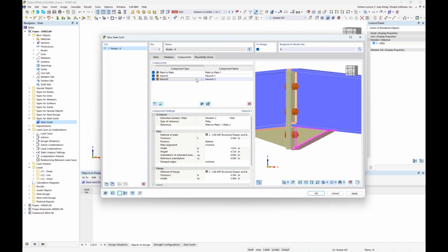We move over here on the right-hand side, and we want to make those exact same changes that we just did to the left-hand side. So we'll modify here the thickness to 0.5 inches. We want to modify the width to 12 and the height to 5 inches. And then we will also want to select no flange here in our dropdown. And finally, we will modify the throat thickness to 0.25 for both of those input options.